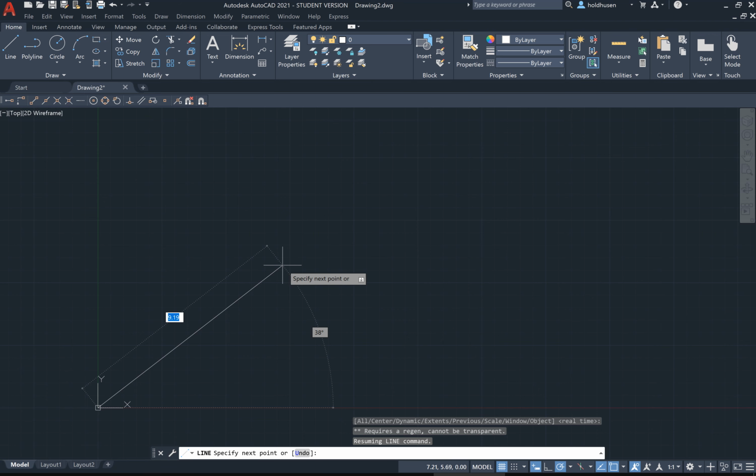So now here's where we have to talk a little bit about our axes. If I want to draw, let's say, a straight line to the right, I started at 0, 0. Let's say I want to draw a 4-inch line to the right. So I would type in 4, 0, meaning I move over 4 and up 0. So I say 4 and then comma 0 and hit enter. And you can see that it created a straight line down at the bottom that is straight over.